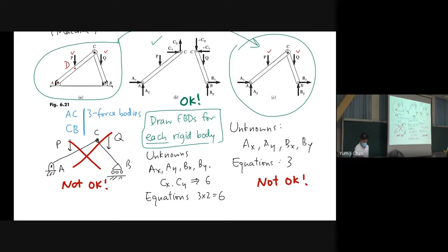Now the free body diagram in the middle also shows us something else. That's for point C. At point C, we have AC and CB, and they meet each other. To determine the forces to draw onto the free body diagram, we first consider one of them, and we put CX to the right and CY upwards.